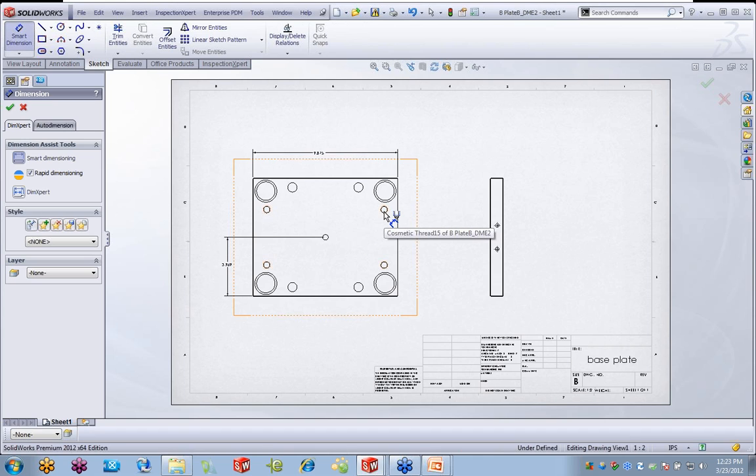But what happens is as I grab something that's intended to be dimensioned, you'll notice that I end up with this, we'll call it a pie, and the pie allows me to select where in the annotation view I want to place the annotation. But notice its spacing relative to the model edge. Even if I go to this bottom left-hand quadrant, the dimension is going to be that distance from the model edge that's specified in your options. Okay, so regardless of which direction you go.